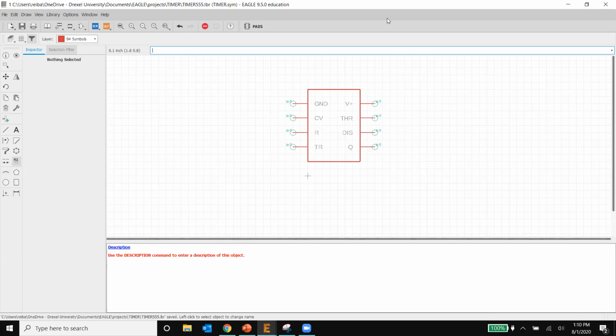And now we have the footprint, which is going to be what goes on the board layout, and this is what stays on the schematic. So that's how EAGLE works. You put this on a schematic somewhere, and EAGLE takes the footprint of that component and puts it on the board layout for you. That's why these two files should be held together in a device.